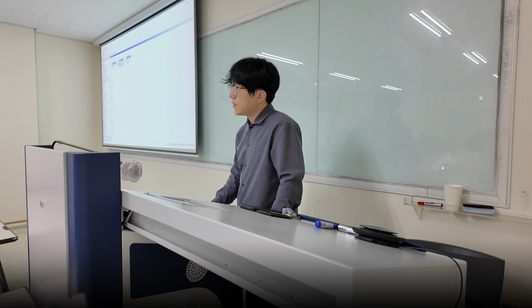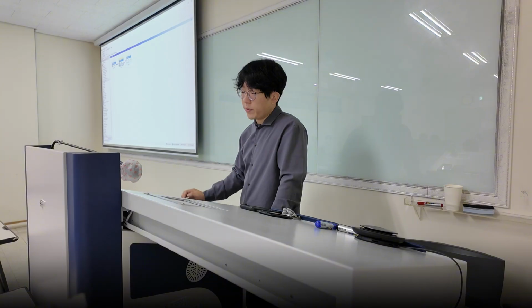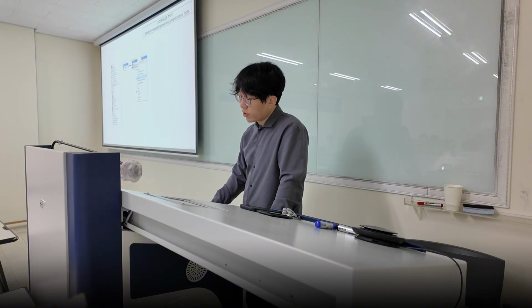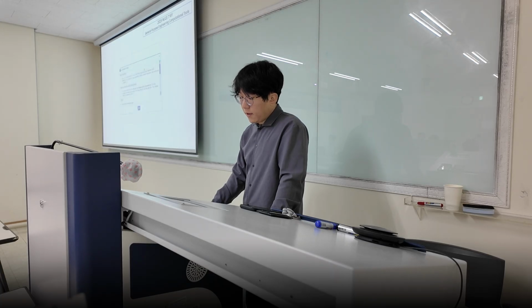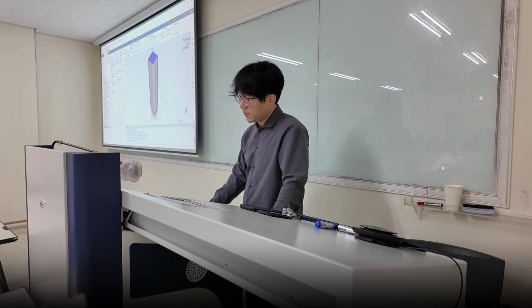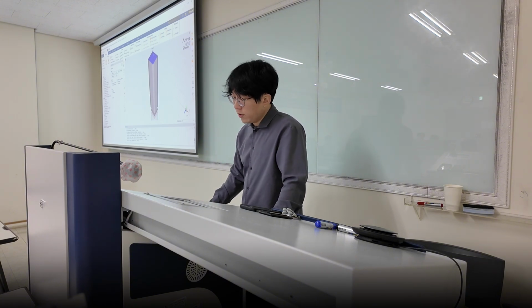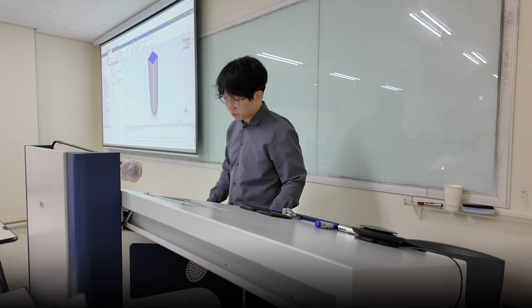You're gonna create a Fluent node, and then connect the mesh to Fluent so it can load the information that you just generated, and you're gonna update it so you can see this check mark. Then you're gonna edit the Fluent setup and allow all the messages. Because we denoted this as inlet, you can see this incoming flow to the surface, and you can check the mesh quality again. It's going to be a perfect mesh.